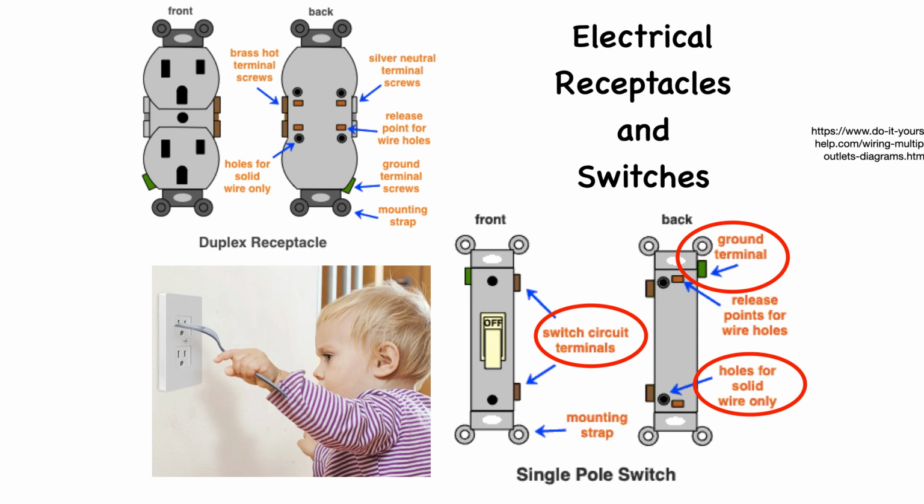Both switches and receptacles are available in 15 and 20 amp circuits, so be sure to use the proper size replacement device for the circuit you are working on. In older dwellings, the devices and wiring may be outdated, and you'll find receptacles that are ungrounded and non-polarized. Always use an appropriate type of receptacle to replace the existing one. For instance, don't replace an ungrounded receptacle with a new grounded one if no ground wire is present.